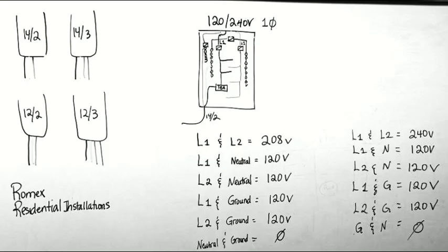So am I within the capacity of the circuit? Yeah. I only put 10 lights, right? And if I take my 15 amps and I divide it by 0.089, it tells me that I have a capacity of 16 lights. And I'm putting only 10 lights on this circuit. So this means that each one of these lights is consuming 0.089 amps. Can I add more lights? Yeah. I can add another 6 lights, right?